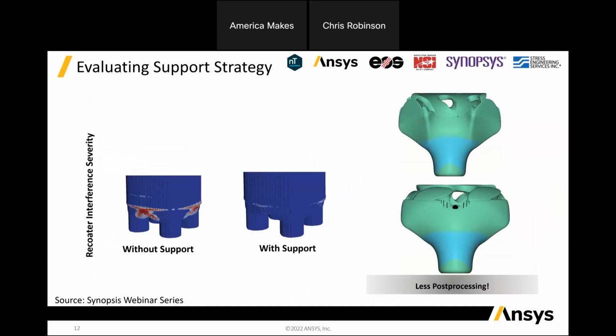Another example, again, kind of looking at this build setup type of process. This is going back to that heat exchanger that I was showing earlier, but the part is designed with the original intent of hopefully not needing supports on that underside. But as you run a simulation, you can see that there is a fairly significant potential on that for this particular geometry to run into some recoater interference. You can solve it with support, as shown in the center. When it's supported, then you eliminate that potential for recoater interference.